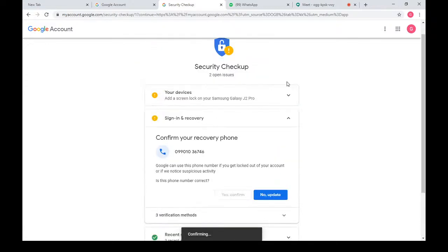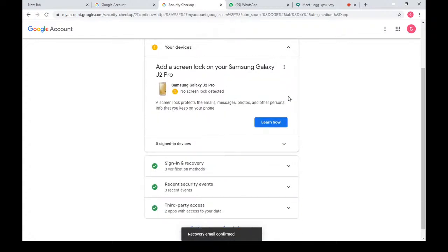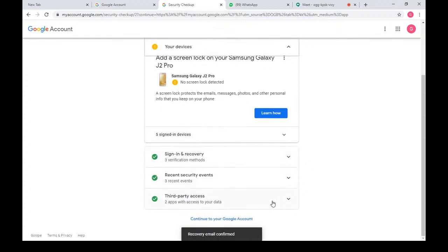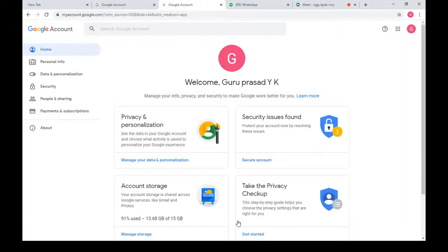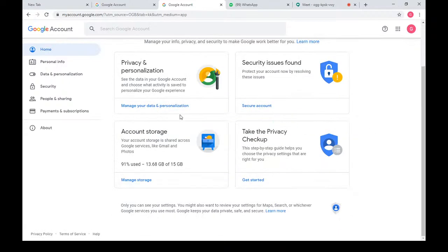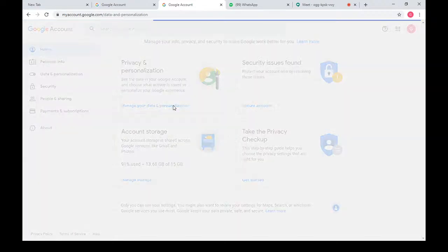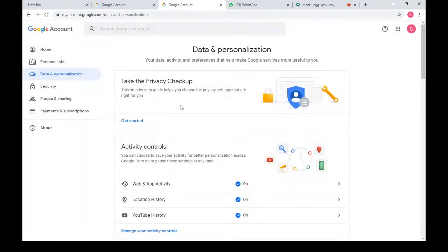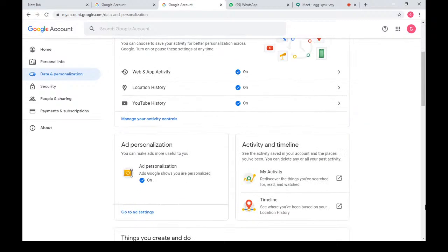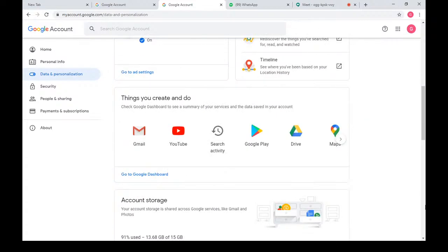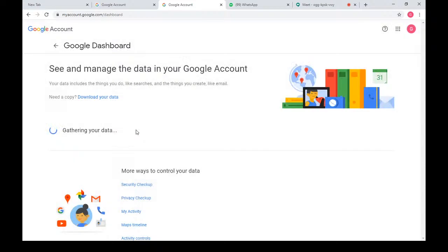You can see the wave motion here. When they pass through the solid bedrocks, you will have a very low amplitude. Again, when they pass through the poorly consolidated sediment, you will find an increase in the wave amplitudes. Again, when they pass through the solid bedrock, sediments or water saturated sand and mud, you can notice that there is an enormous increase in the amplitude of the wave motion. So this will affect the structures resting on the ground surface.